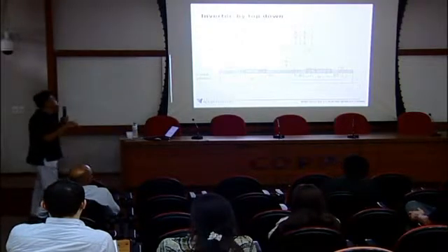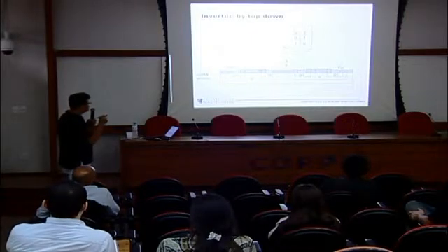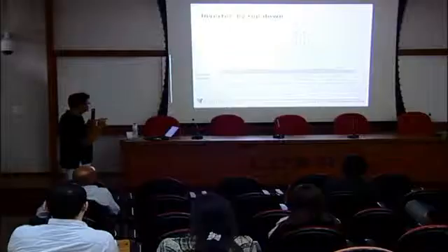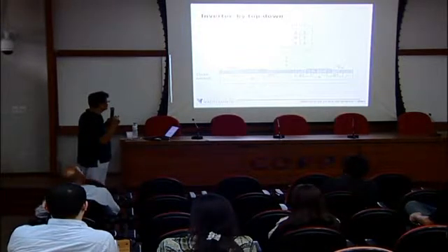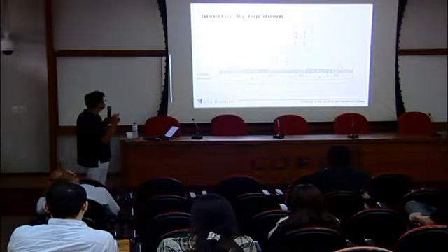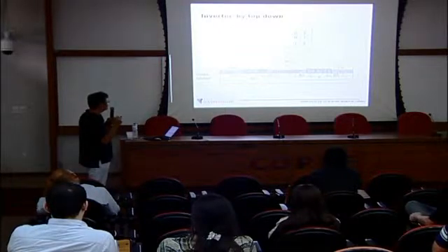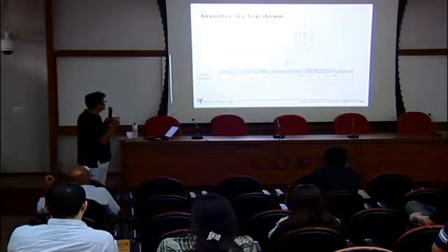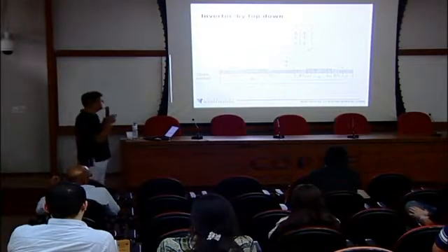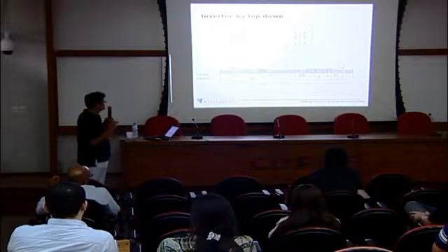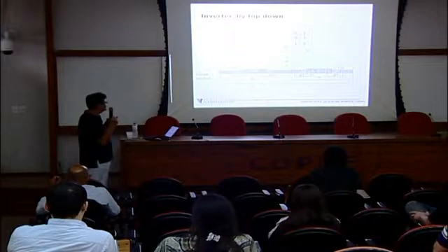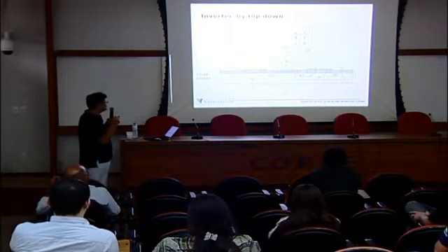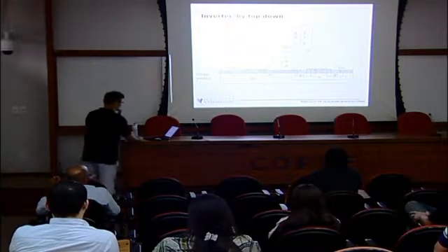This is the actual structure of the inverter. Okay. So if you see here, this part is an NMOS, and this part is a PMOS. There is an electrode with this one. It will be coupled with a 0, and then there is a common electrode. The gate A is here, and then the 2 electrodes in the N well and P well are connected to output Y, right? And then VDD, that's the electrode out there. So NMOS and PMOS are combined. So if we give a signal to the gate, then output will come out from there.